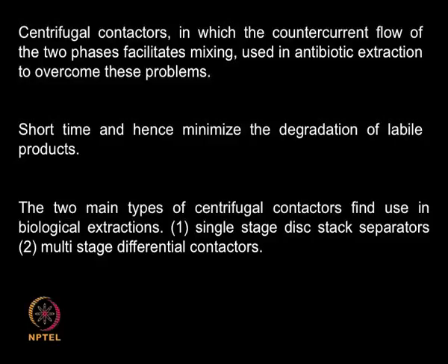The advantage is that it is going to be a shorter time, because separation can be achieved because of the high forces you are using. It is practiced in extraction of antibiotics from the fermentation broth. There are two types of centrifuges we can resort to for biological systems. One is the single stage disc stack separator, the other one is the multi-stage differential contactor.